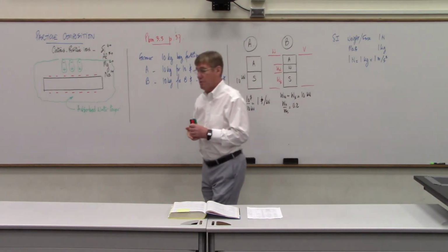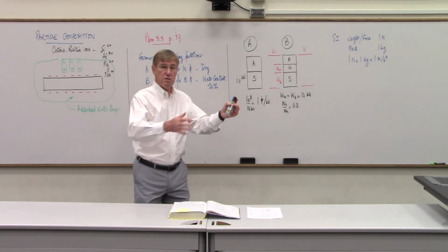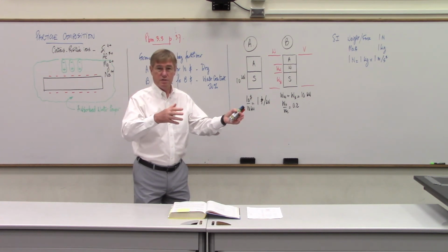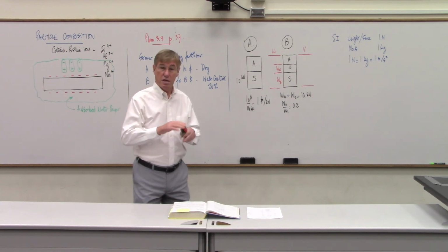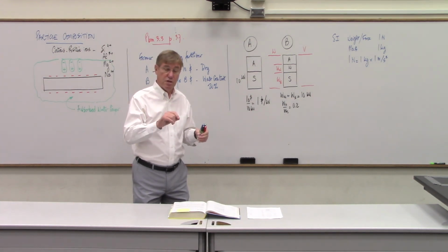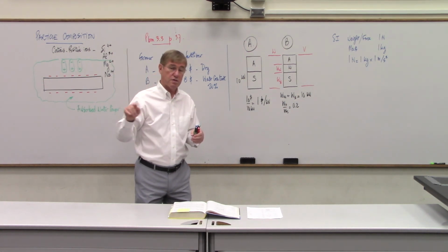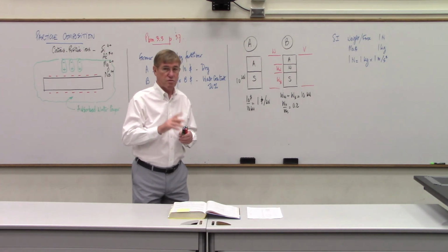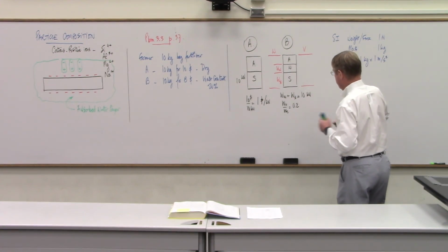You might have been tempted to say, well, 20% of 10 is 2, so that'd be 2 kilonewton. That's wrong, because if you did that, you would take weight of water over total weight equal water content, and that's not the definition of the water content. Water content definition is weight of water over weight of solids. So remember that.